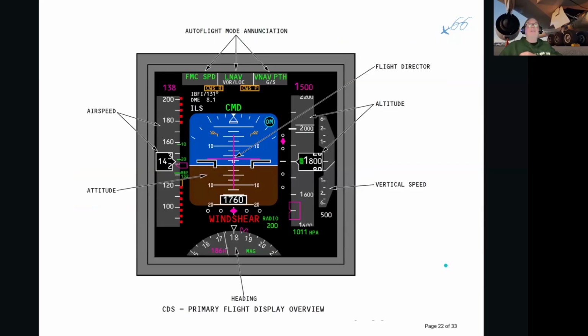And this is the PFD, the primary flight display. This is used for short-term navigation, or what I call up, down, left, right. That's what it's for. We go up, down, left, or right. This is for short-term immediate navigation, what the pilot immediately needs to do to navigate the aircraft. I have the airspeed tape here. I have the altitude tape here.